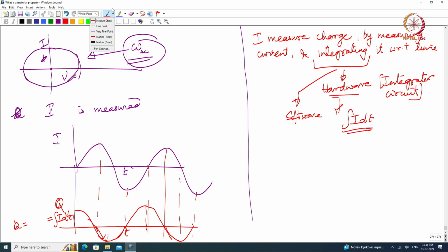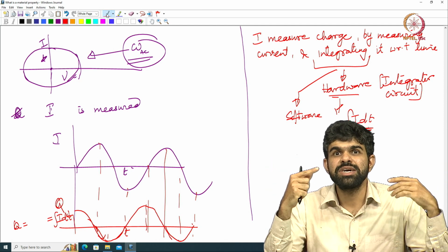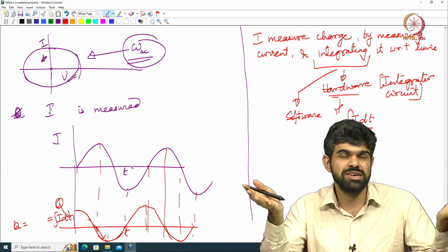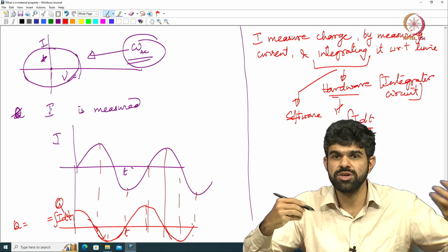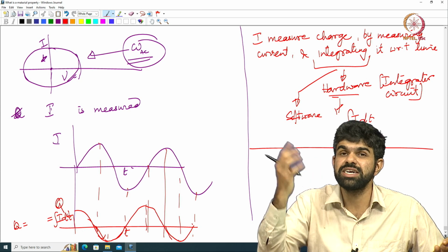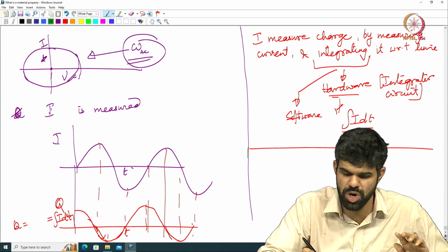Okay. So, the charge measurement or the capacitance measurement has slightly more details than, let us say, a piezoelectric measurement, because in piezoelectric measurement I can directly measure the displacement. But in capacitance measurement I would not be able to directly measure the charge, I would measure the current rather, the differential of charge. Then using the differential of charge I can integrate that and get the charge. So, I will measure current and I can get the charge. That is the small difference.